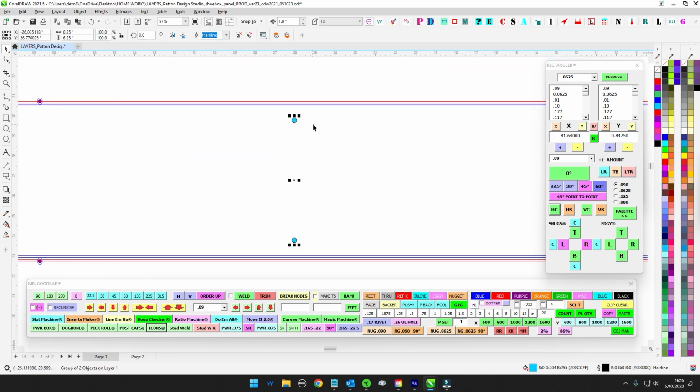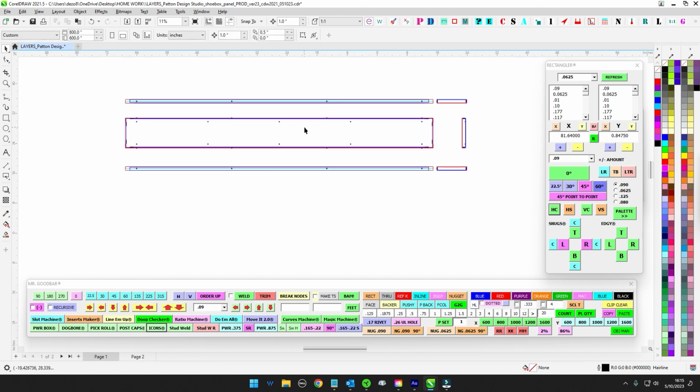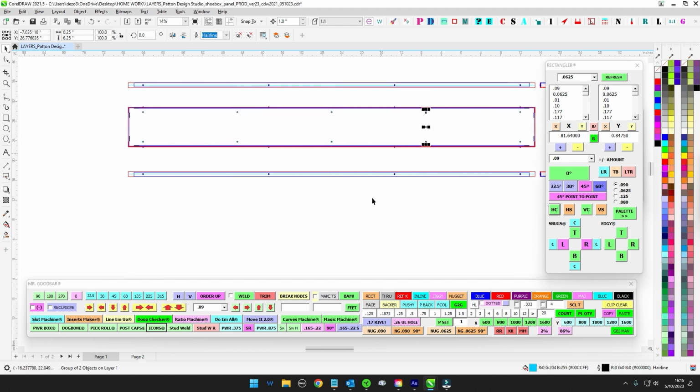And what they'll do is they'll shoot a screw here, and then level it, and then shoot a screw here and shoot a screw here. So sometimes it's better to add a little extra. 2 more holes isn't going to kill anybody. Also, install can then make the choice where maybe they'll put these 2 in, and then put 1 here, maybe 1 here, and then 2 here. You know, they can also make good judgment calls.